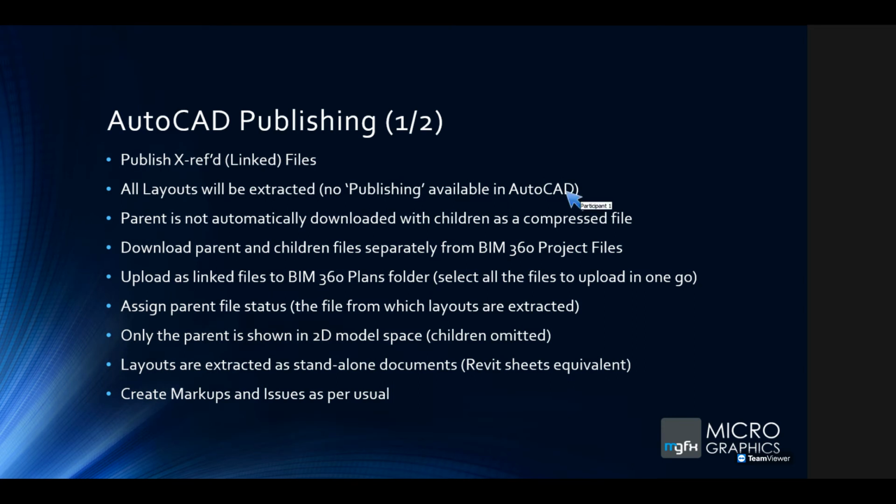And the next item that's up is AutoCAD publishing. So I chose a simple AutoCAD file, which I generated from some exports from Revit, but it does expose a more complicated workflow in the sense that we're going to see how one AutoCAD file is XREF'd into another file. So XREF, external references. Those of you that use AutoCAD will know these.